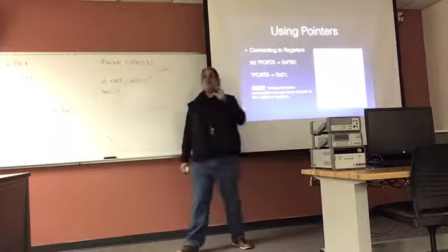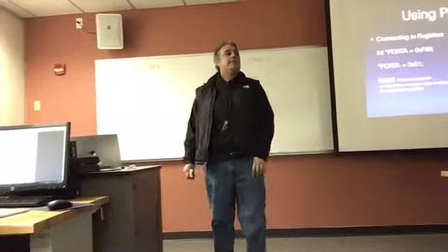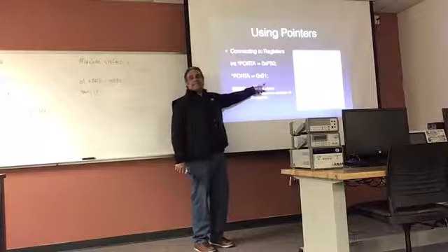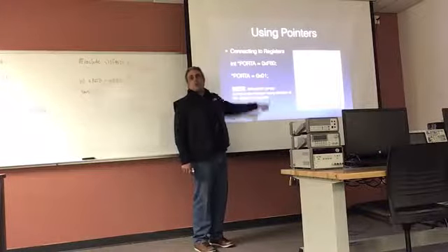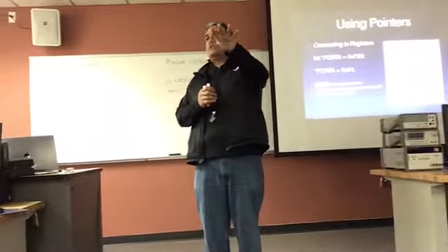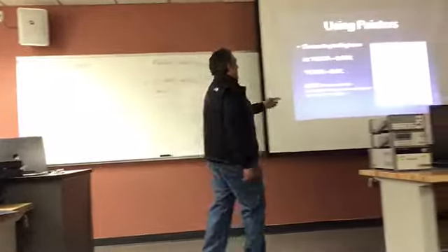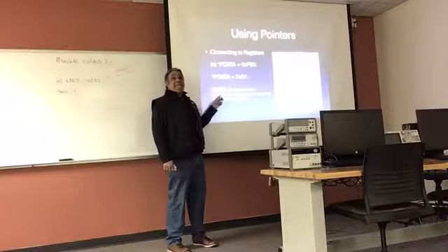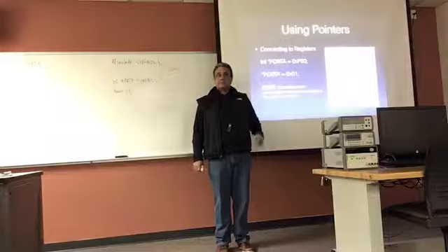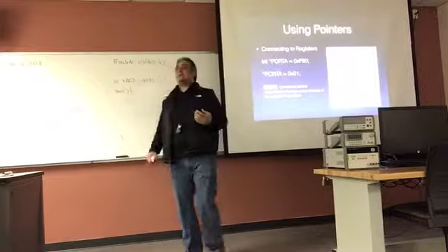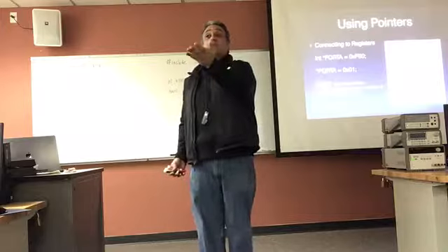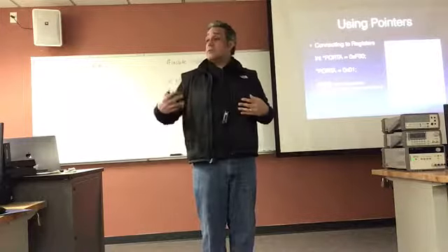Okay. What's the problem with this? The problem is that every time you use an unmasked operation, what I mean by unmasked is that I'm taking the value and sending it straight into my pointer. You are manipulating every single circuit inside of that register. An unmasked operation creates a maximum amount of change inside of that register. And you already know that this register is a collection of individual circuits.